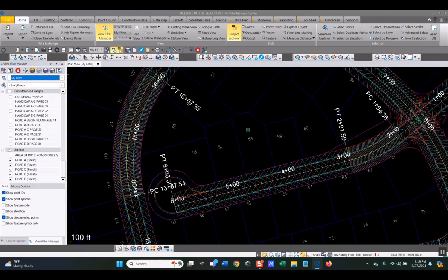What we are going to do is look at several of these: selecting by layer, or picking individual entities by pressing and holding the control key, or just using the mouse itself and making either a solid rectangle from left to right, or a dashed rectangle from right to left. The difference is select by window when it's solid and select by crossing when it's a dashed rectangle.